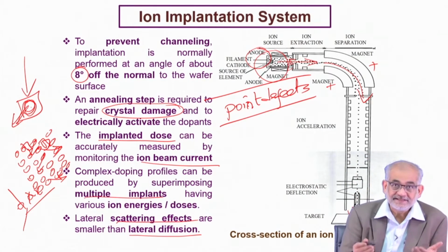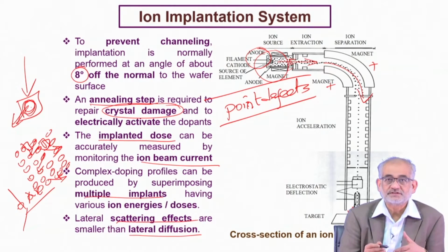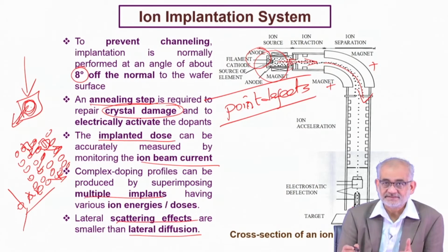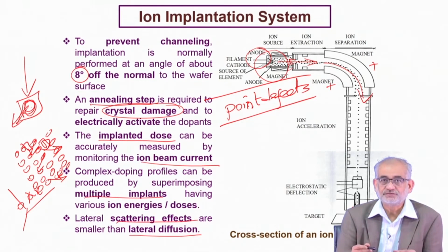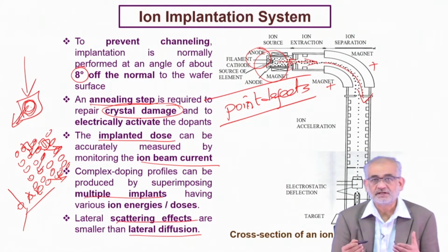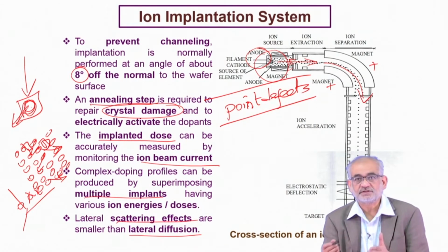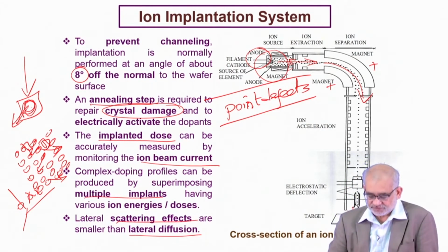So in order to anneal out those defects, many of these semiconducting devices and wafers are subjected to certain post-implantation annealing, a thermally activated annealing process, whereby the atoms will come back to their respective crystalline positions. That means you'll restore crystallinity, and that also will improve the conductivity and ensure structural stability in future.